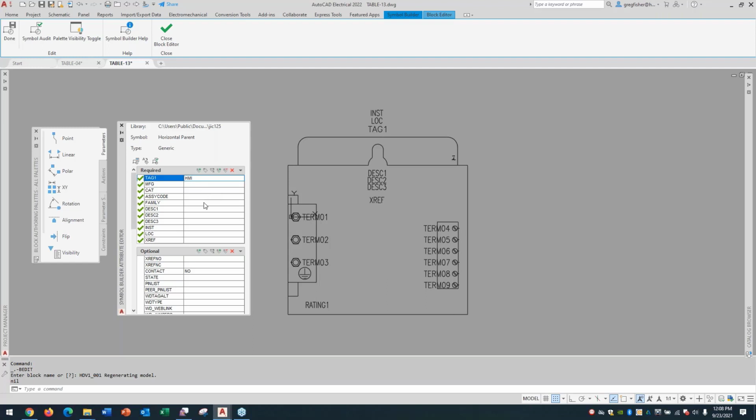Now, typically, and I try to drive this home during class, your family code should be considered whatever your table is in the parts database. It's not the end all to be all, because what ultimately determines the table that you're going to access through the catalog browser is the actual symbol name itself. But I try to keep the family code the same name as whatever table I'm going to use in the parts database.